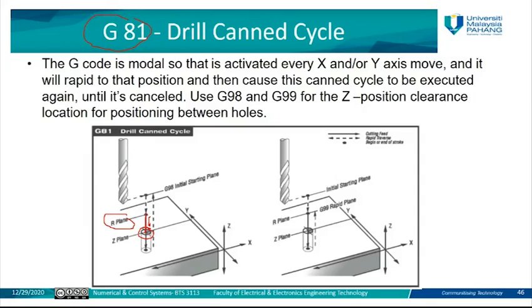Then create the first hole, then it goes up again to the same R plane here. So it will go and stop here for a while, then go for the next hole and create the next hole, and go to the R plane again, and then go to the next hole and so on.